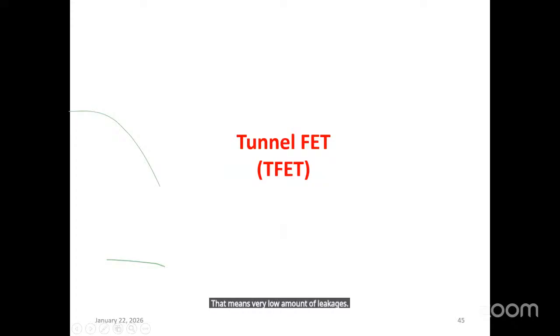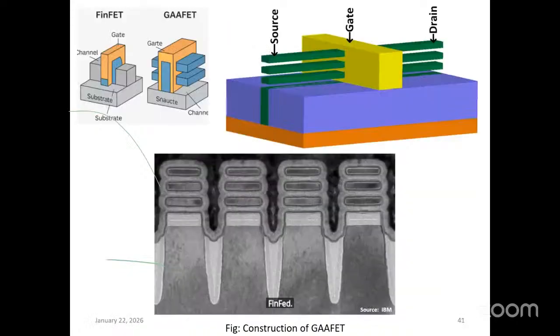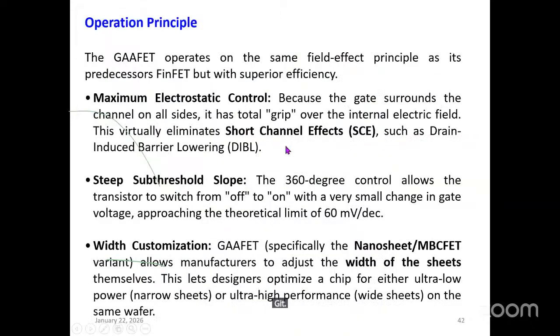I will go again for a recap of the GAA FET. Gate-all-around FET is a derivative of FinFET. The channel is surrounded by the gate. Good control over the drain current, therefore good control over leakages.